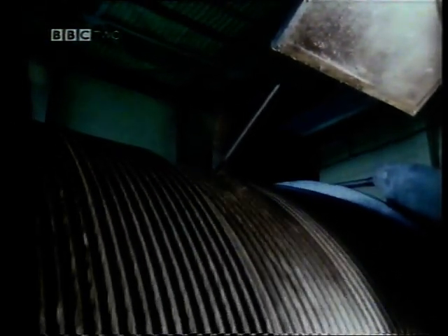So the loading on the cage and the kinematics of the lift determines the maximum tensile load on the rope. This information determines the diameter of the rope required, and in turn the rope size will determine the minimum drum diameter to allow for rope bending. The drum itself carries not one but two ropes, counter-wrapped, so that while one is wrapping, the other is unwrapping. This means when one cage goes up, the other goes down.